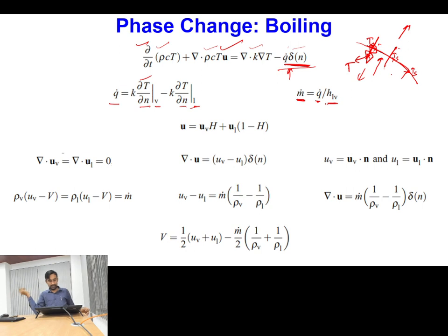Okay, now one small issue: I have told you earlier that near the interface, if I don't have any mass transfer, then my velocity in fluid 1 and velocity in fluid 2 will be the same. So when I am not having a phase change heat transfer situation, then for the entire cell, though it contains the interface, I can specify a single value of the velocity field.